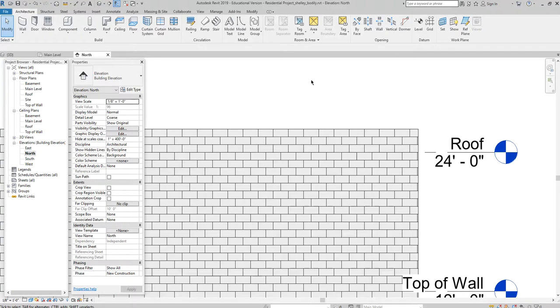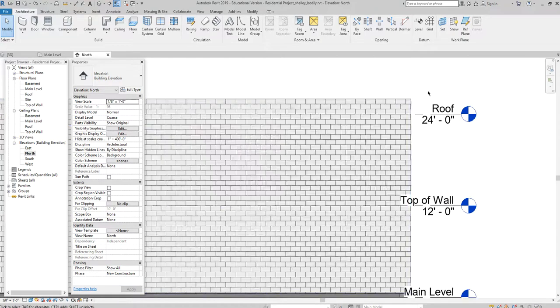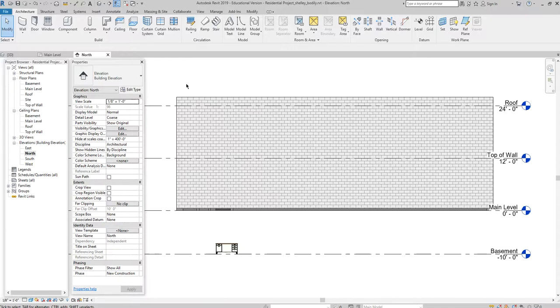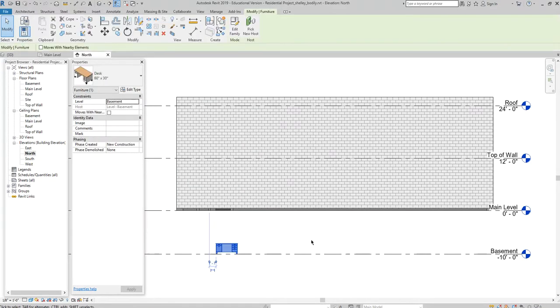One important thing I want to remind you of is that walls should never really be undefined in Revit. Even if you know that the wall's 20 feet, assign a level at 20 feet and assign your wall to live between a bottom constraint and a top constraint, which is 20 feet. Don't ever leave your walls unconnected. It means they're undefined, and if things change, then they don't change. Okay. All right. So we know how, look at our little desk hanging out down there.